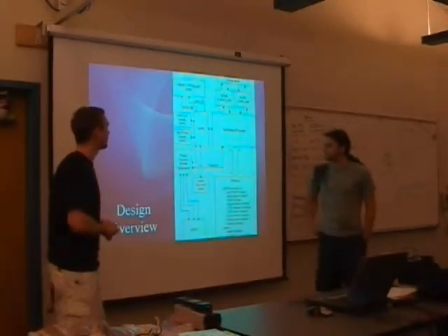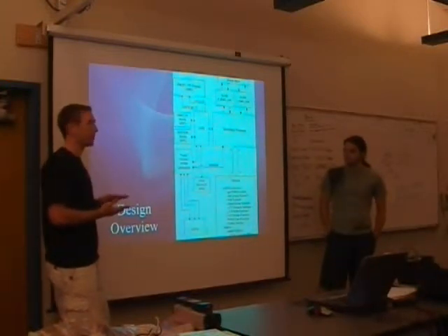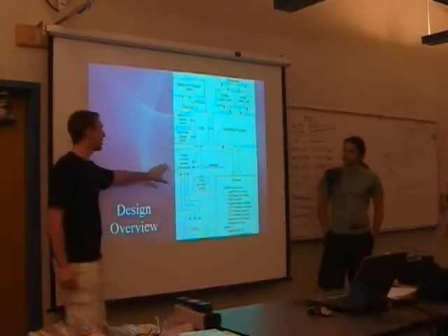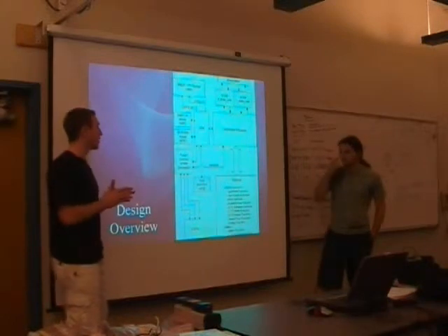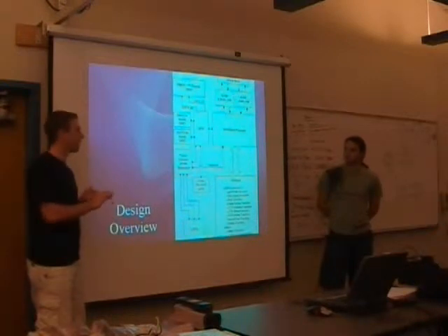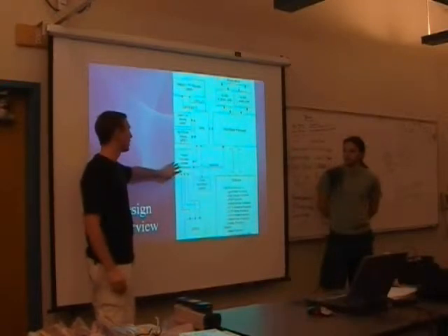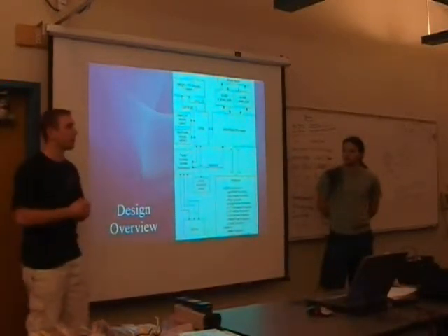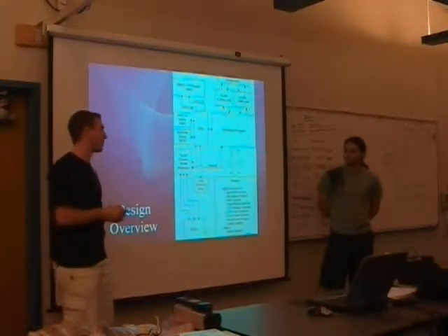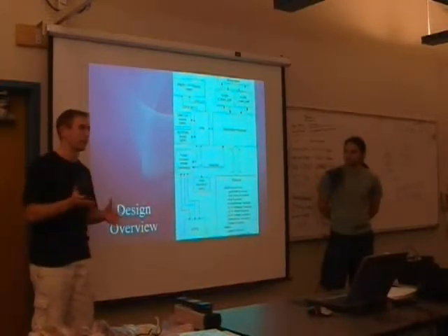The software part is basically the base setup for the function generator lab, where you have the timer counters doing frequency generators. Instead of doing interrupts off of that, you use the PWM output of the timer so that you get your 3 different RGB pulses out of it. There's also an interrupt from a 4th counter that acts as the output frequency generator, which is how fast you want your LEDs to output the colors you're sending. It's anywhere from 30 hertz to 60 hertz and then 1000 hertz, just so you can see the differences between them later.